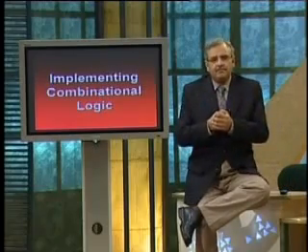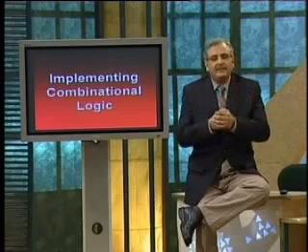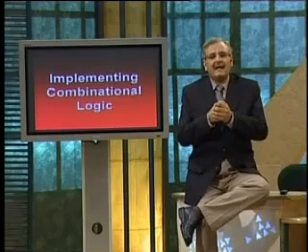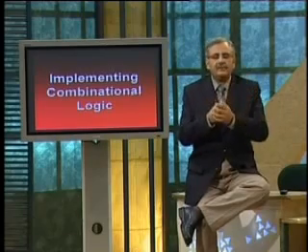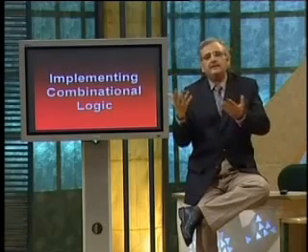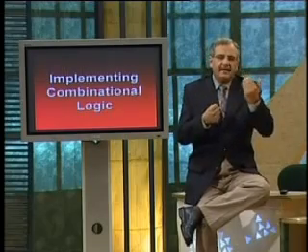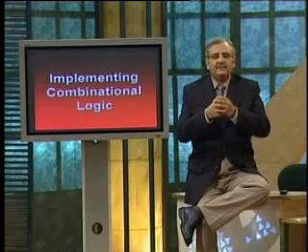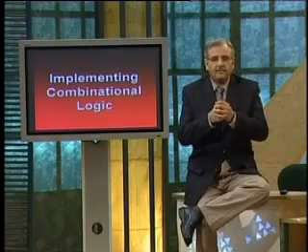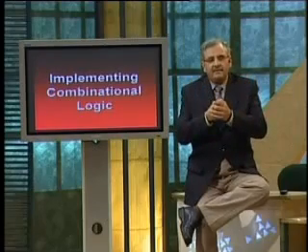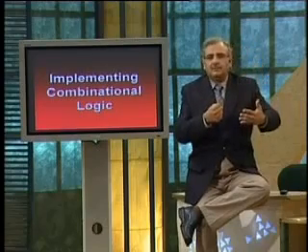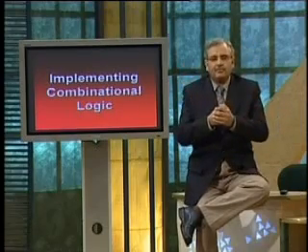Let's take an example, the example of a 2-bit adder. Now, what does a 2-bit adder do? Basically, it adds two numbers and each number is of 2 bits. The answer would again be of 2 bits, but a carry might be generated. So basically, the function of a 2-bit adder is to add. Okay. How would you represent the function? Basically, you would draw out a truth table where you would have all the possible inputs and the outputs.